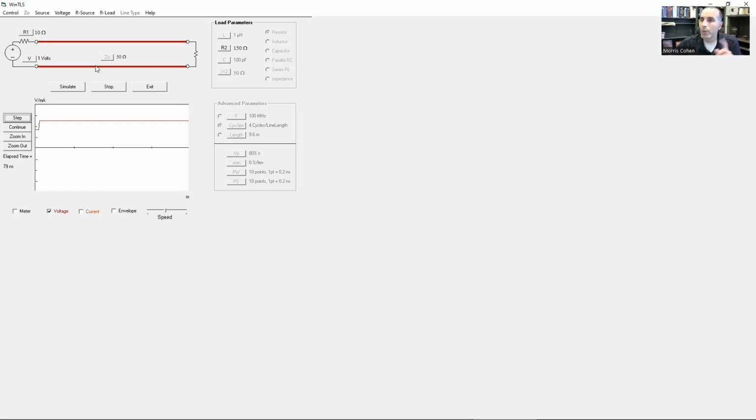So ask yourself the question right now, what voltage is going to work its way back in the positive direction after this reflection? Right, so we know that 2/3 is going to be there, but what are we going to multiply it by? Our two choices are, it's going to be the entire voltage on the transmission line, or it's just going to be the voltage of the reflected wave only. So think about that for a second. Pause the video if you'd like to.